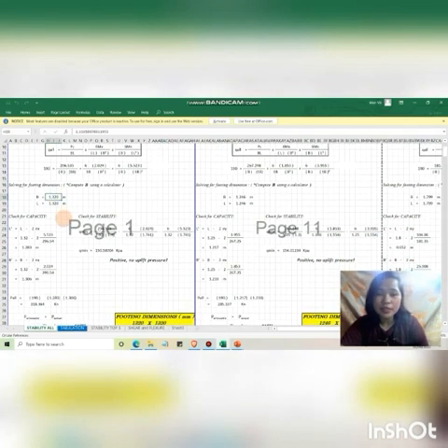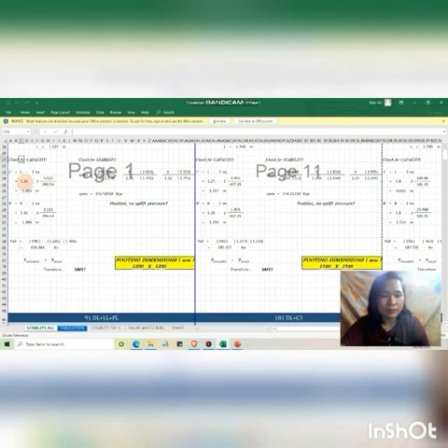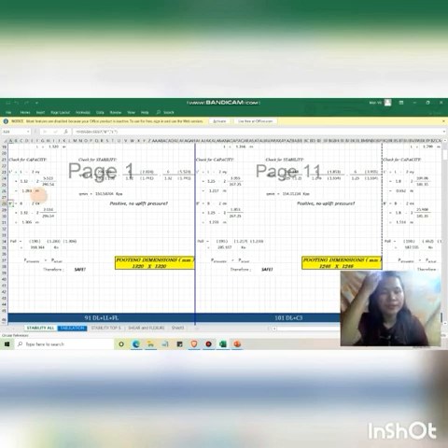Checking for its safety, first we will check the capacity, with the formula P allowable is equal to the Q allowable times the effective area. For our effective area, we will use our effective length and effective base dimensions.